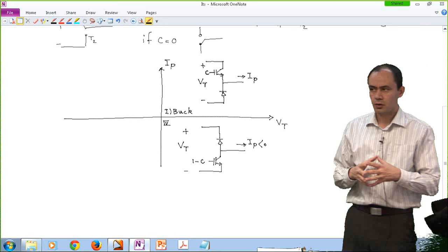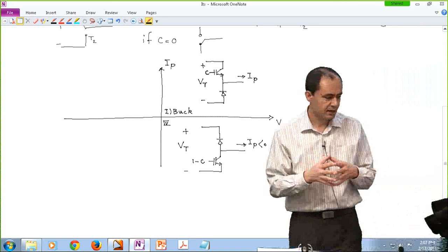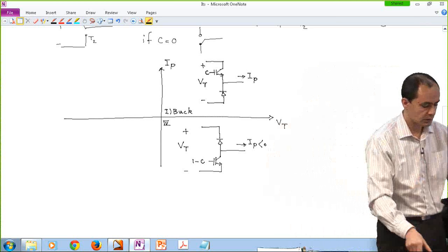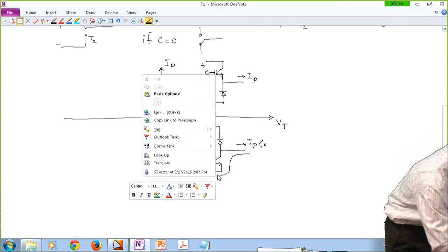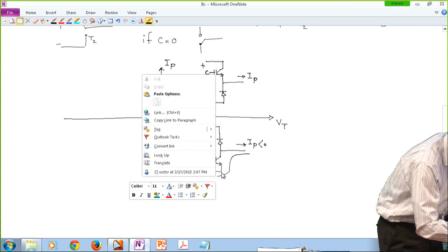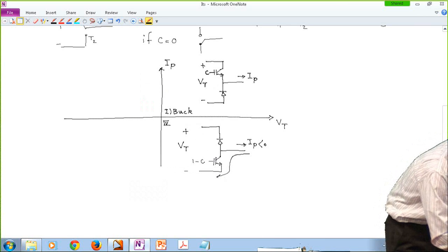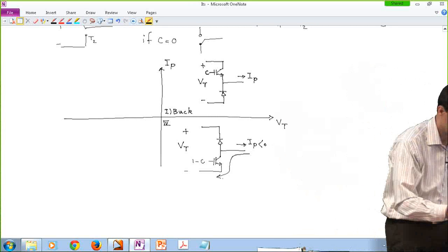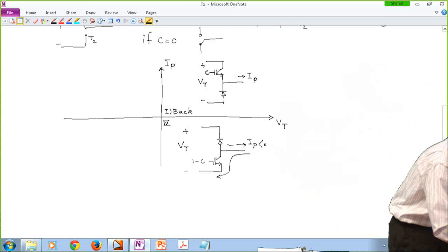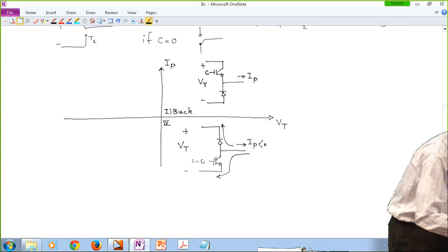Okay, so if the pole current is negative and we want the bottom throw to be active, basically we have to turn the switch on. Then the current is going to flow in this direction. And if we keep the switch off, because the pole current is negative, it is going to actually push the diode to be on, so it's going to flow in this direction.